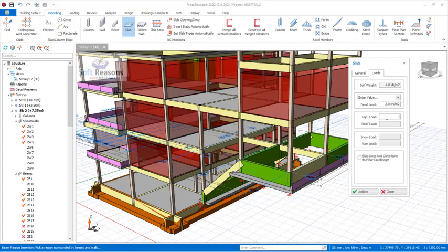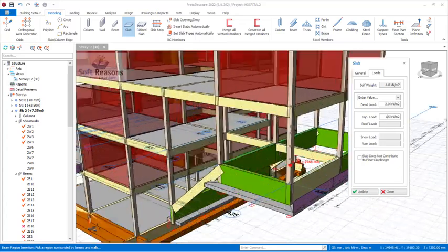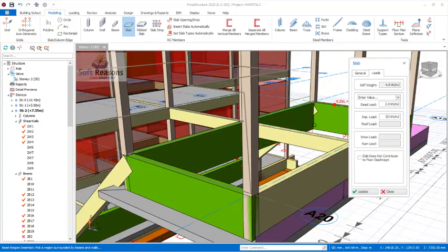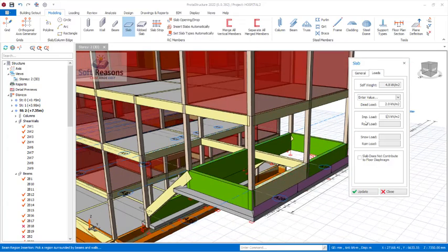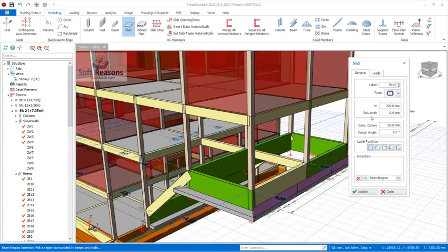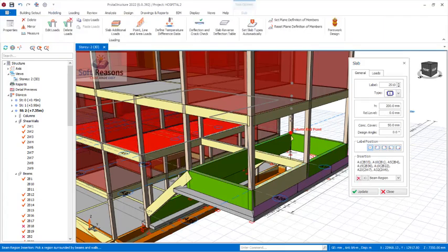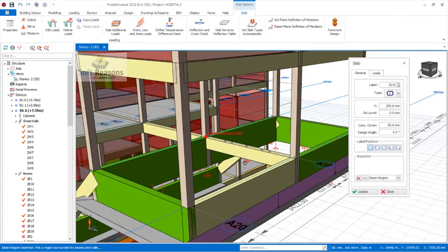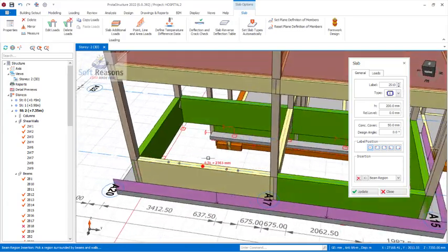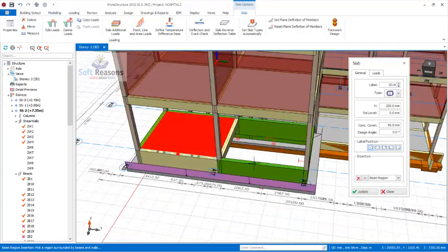This is a residential structure, so we can use 1.5. Now if you place your cursor in the air, you can insert this slab. If you check over to General, you notice that your relative story is 0, so it's going to rest directly on top of the provisions. Make sure you update it in the right way and place your slab just like this.